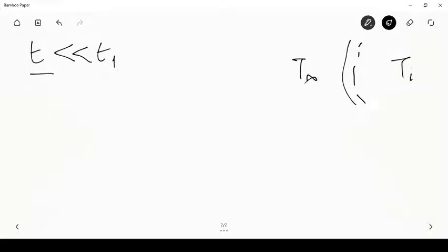And if I take this as the x coordinate, then as x tends to infinity, temperature becomes Ti, and the finite values of x inside this domain, where the temperature variation is happening and therefore you actually need the solution of the equation, that region is much smaller as compared to this. So delta is much less than, let's say, R0, which is a typical characteristic dimension of the body.